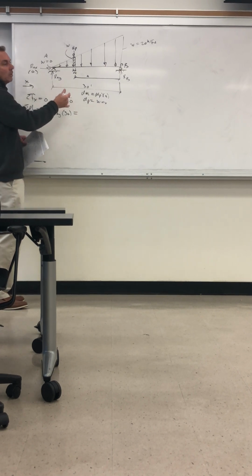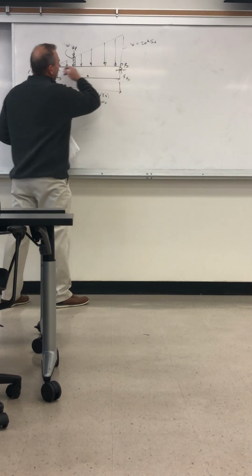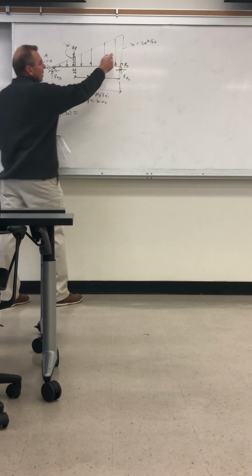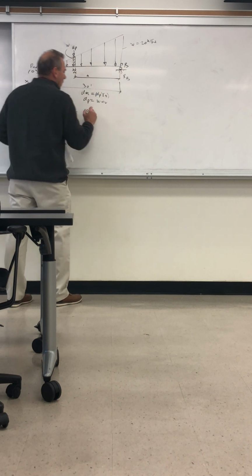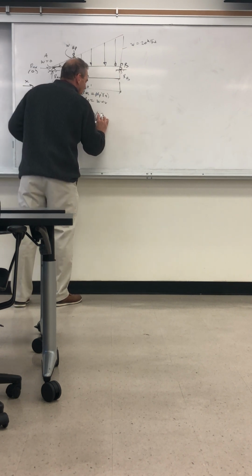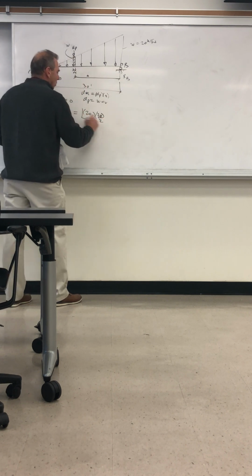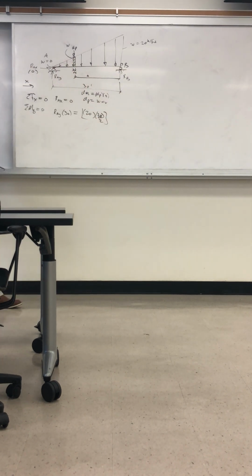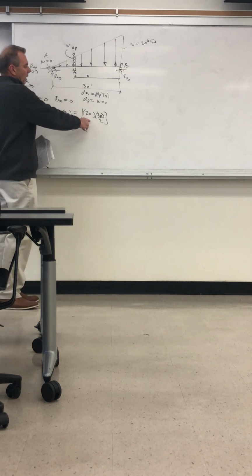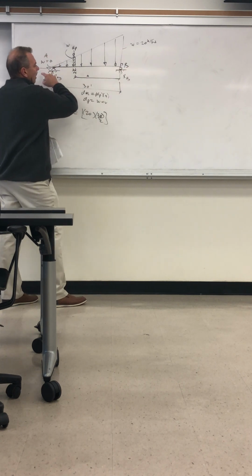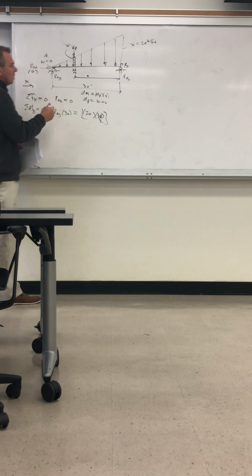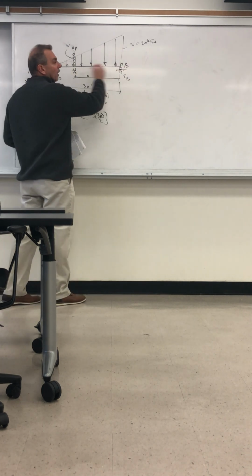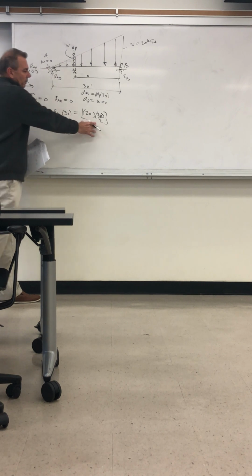So this time, instead of doing that, we're just taking the total area of the distributed load. So imagine it's the area of a triangle. It's 20 kips per foot multiplied by the length of 30, divided by 2. So that's the total force applied. This would be in kips, right? This is kips per foot multiplied by a distance divided by 2. A distance is in feet, so this is a force, the total force down. It's the same as if we integrated this part of it.